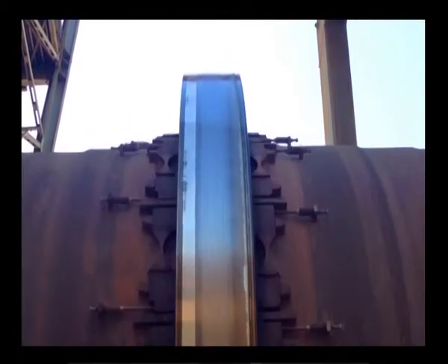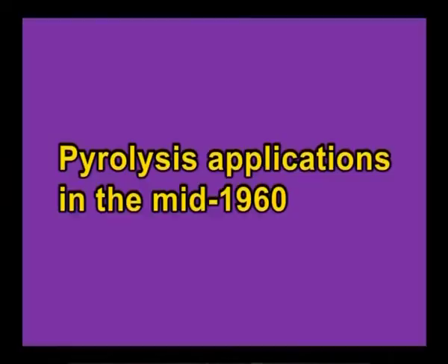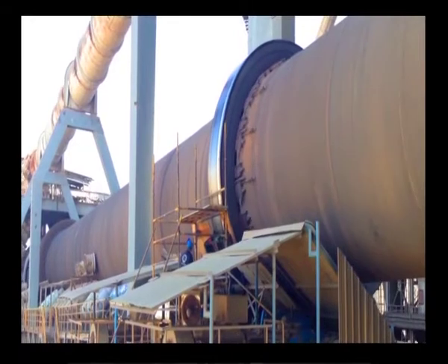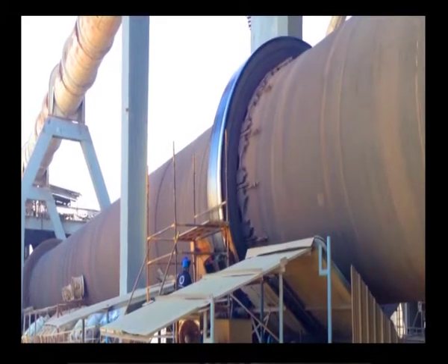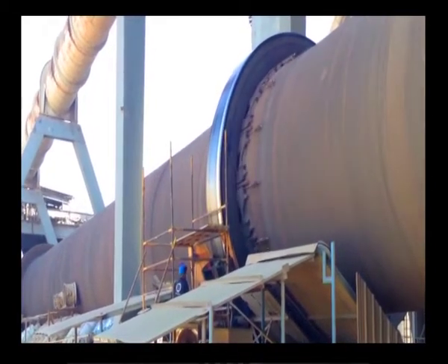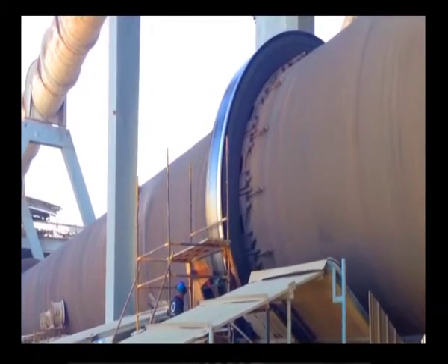In some instances, special provisions have been made for air cooling or water cooling the kiln shell, thus eliminating the use of refractory. For example, a steel kiln cooled with external water sprays, known as the Lance converter, was developed for pyrolysis application in the mid 1960s. In the later 1970s, a new kiln technology emerged involving a water-cooled kiln cylinder fabricated of steel boiler tubes welded together and manifolded for the introduction of feed water and withdrawal of steam.